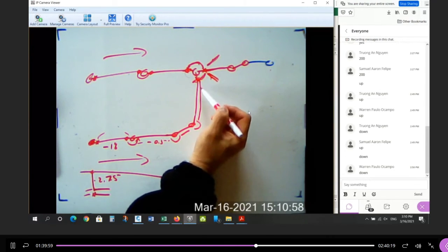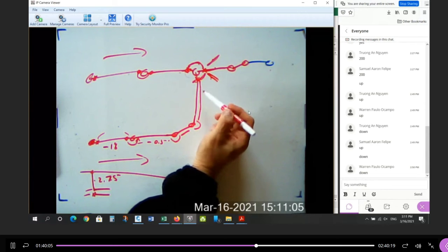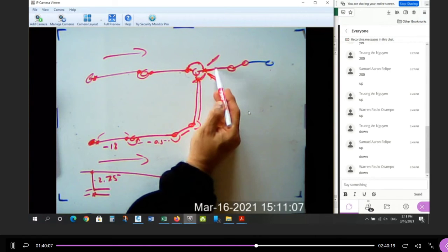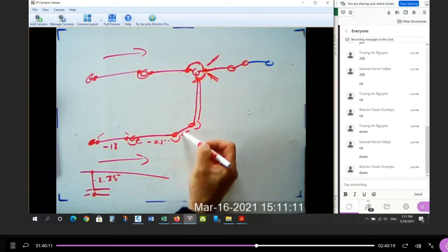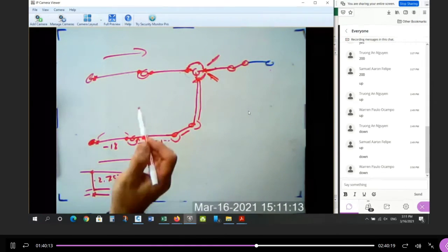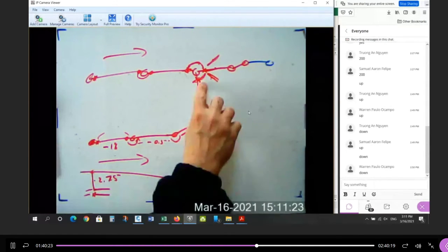And the minimum drop, again, is going to be based on exactly what I taught you last semester. The difference in pipe size between the up and downstream, and the angle. Is it straight through? Is it 45 degrees? Is it 90 degrees? There's always two options for the minimum drop. Difference in pipe size, minimum drop based on direction change. Okay, we'll look at those in a moment. And then you continue your way down.